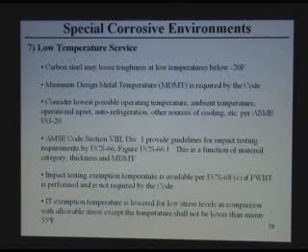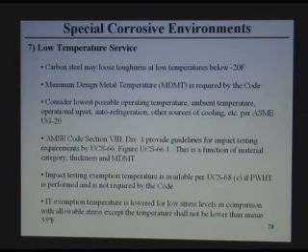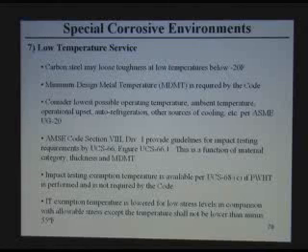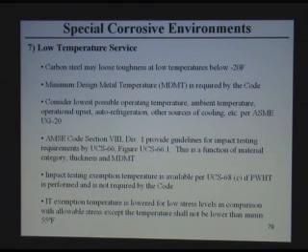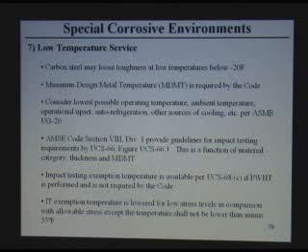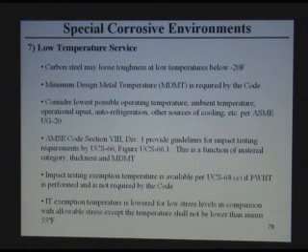The ASME code provides for certain impact testing to make sure that the material is tough enough at design conditions. To ensure that the steel is good enough, you have to impact test it. The impact testing requirement is spelled out by these figures. If you are below the curve, I show the curve, you don't have to impact test.